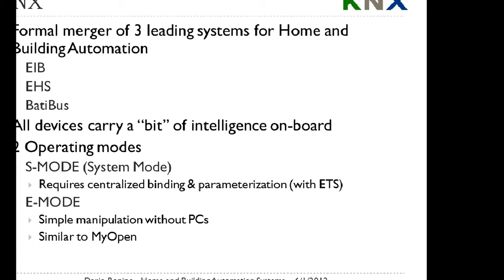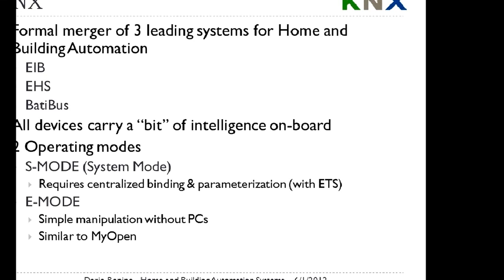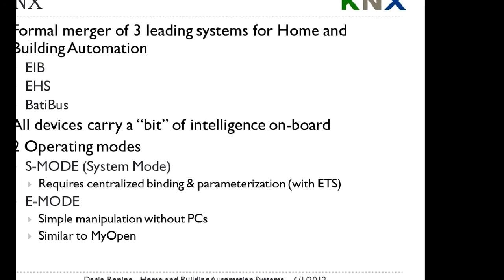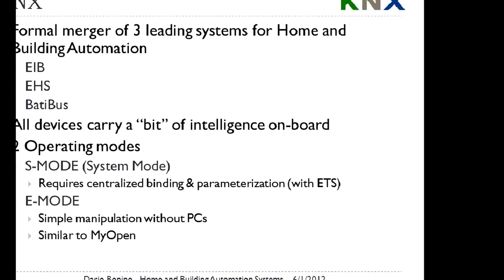And this is one of the most difficult things when we work with KNX, because the device can come without any program and we can download on the device some different program depending on the needs. But if you do that, you are encountering problems, for example, with versions. One version is not compatible with the other. With memory, maybe the new program is too big for the memory on the old device, and so on. Okay? So they are adding additional complexity to the programming side.